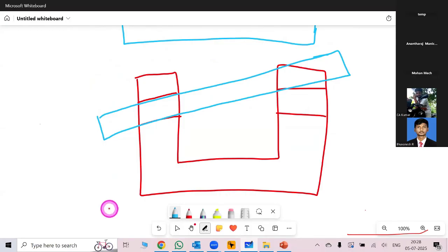So in such conditions, we use this concept called projected tolerance zone, wherein we project the tolerance zone outside the material so that whatever tilt you're seeing here can be reduced, and then you will be able to assemble the pin into the part easily. So the method of reducing this tilt is the projected tolerance zone. For today, I think this is sufficient. If you want to know how to use that and how to reduce that tilt, it would take some more time for me to explain. We'll take it up some other day.